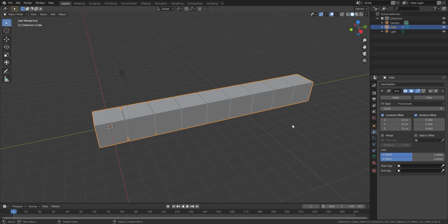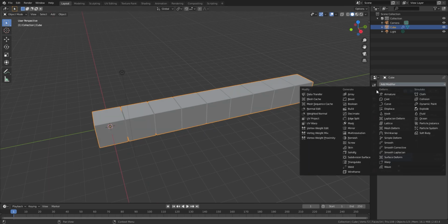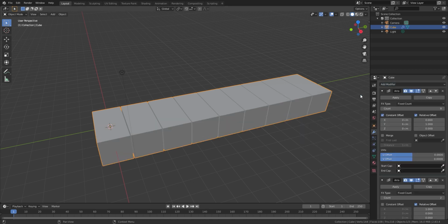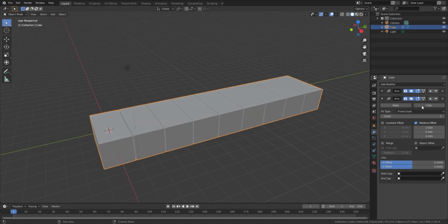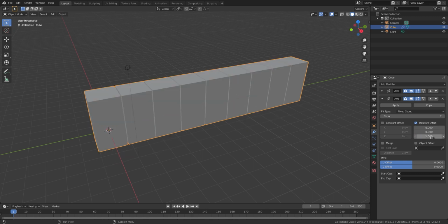Then we add another array to this. Be aware that it has been moved beneath the previous one, so don't go on an amok run in the upper section. Simply close it and scroll down. We want to move the row upside, so z-axis is set to 1 unit and x needs to be set back to 0.